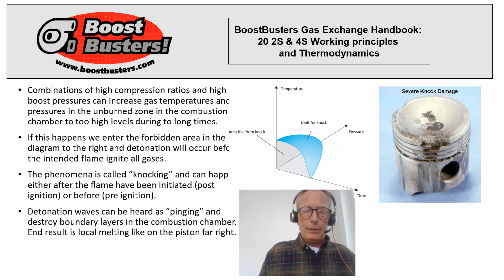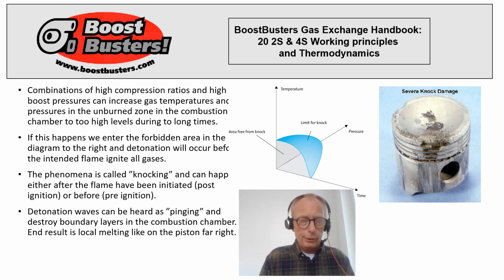Anyway, especially in high compression engines using maybe some kind of charging device, turbo, supercharger, there is a potential danger that the flame in the spark ignited combustion system is not able to light off air and fuel in the way we plan for.